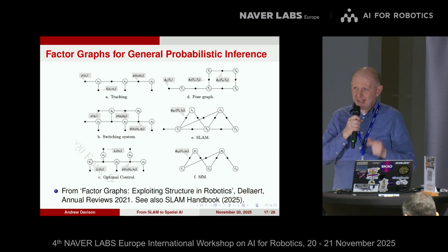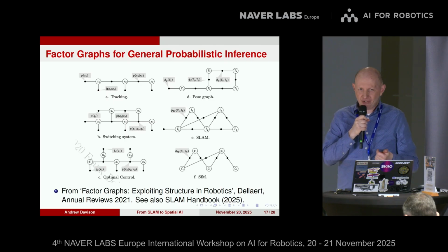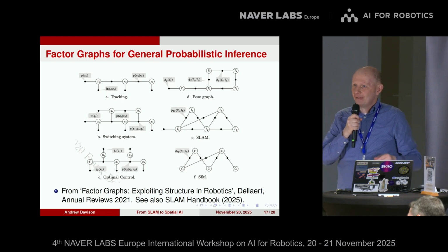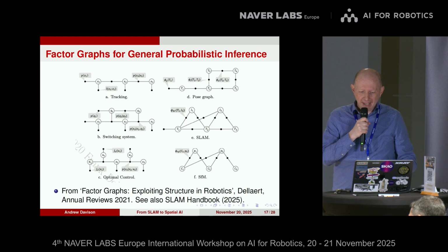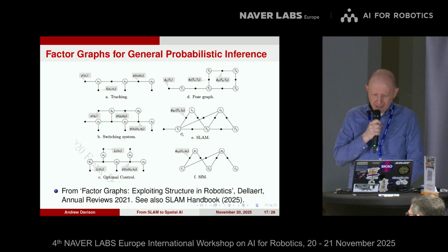So once we are thinking about this type of computation, where in general I think we want graphical structures of our algorithms and our data structures, and as far as possible we'd like to do computation in place on those structures, it takes you back to thinking about the algorithms that we've always been using in SLAM, which have always had this graph-like structure. In particular there's this probabilistic graphical model formulation called the factor graph, which is the key thing that we always go back to in SLAM.